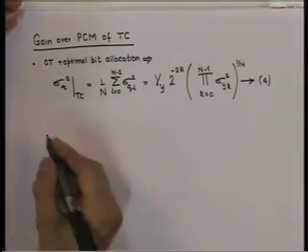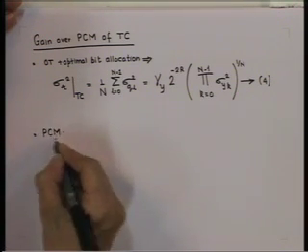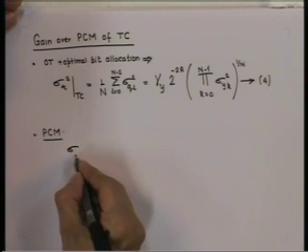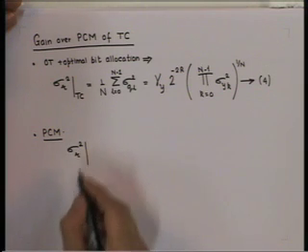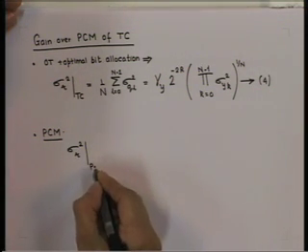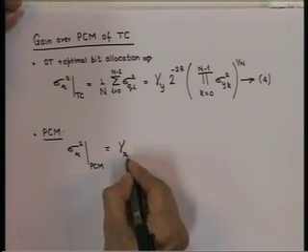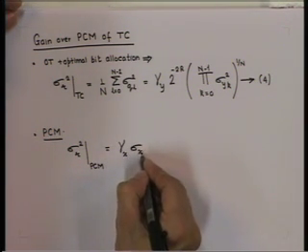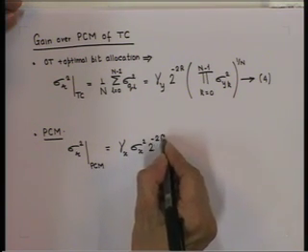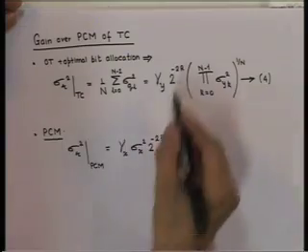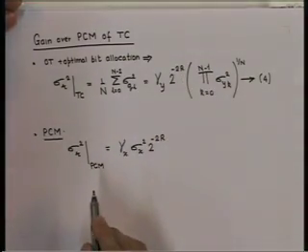Now, compared to uniformly quantized PCM, we have the quantization error, equal to reconstruction error for PCM, equal to gamma x sigma x squared 2 raised to minus 2 r, where we are assuming the same fixed average bit rate.